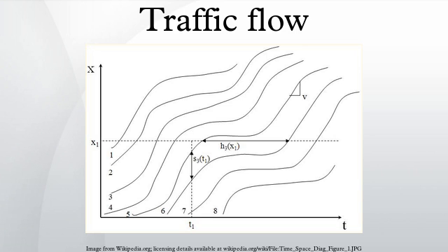The UK's TRL has developed junction modelling programs for small-scale local schemes that can take account of detailed geometry and sight lines: ARCADY for roundabouts, PICADY for priority intersections, and OSCADY in TRANSYT for signals. Many other junction analysis software packages exist, such as Sidra, LinSig and Synchro.